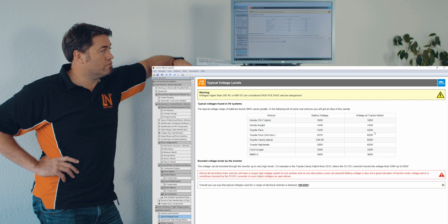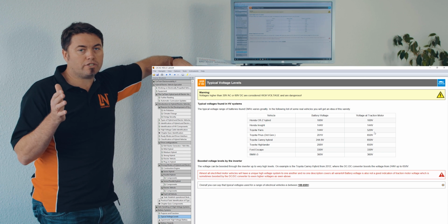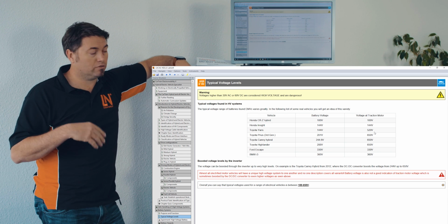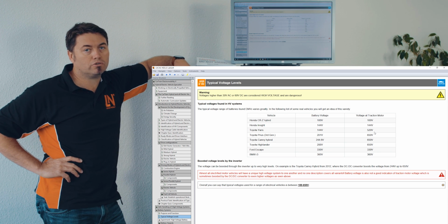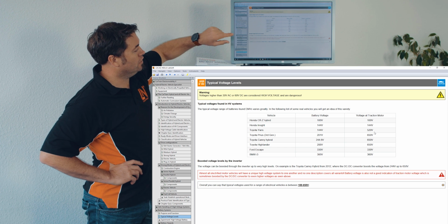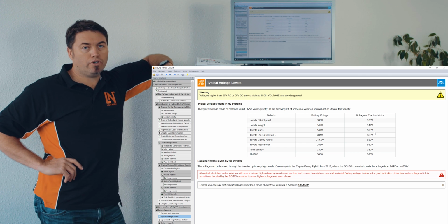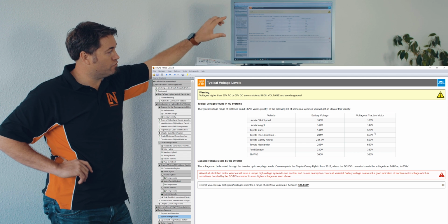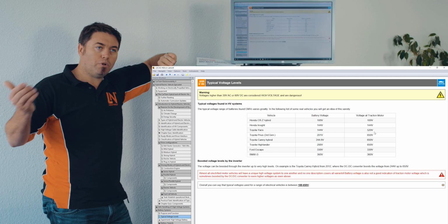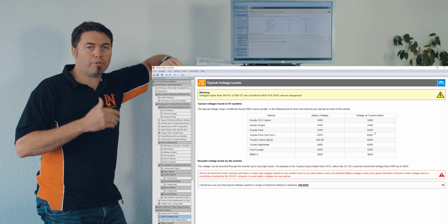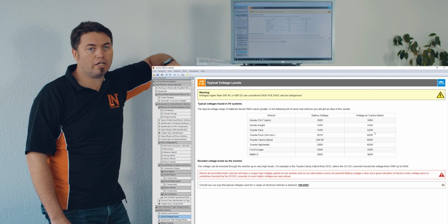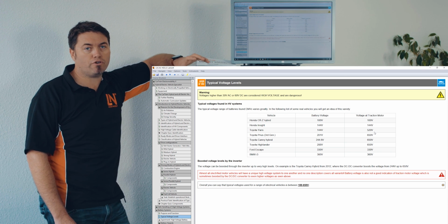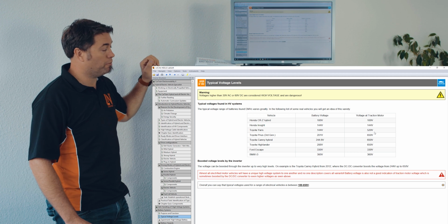And that's not always the case. It's not exactly always 600. It's varying in between. I'll also go into a little detail about that soon. So that there is what we call a buck boost converter. It's converting the voltage up or down. In one direction from the battery, obviously up to the motor. But when the current is coming backwards, then it needs to drop that voltage down again to charge the battery. Obviously, if we have 700 volts on a 200 volt battery, it will probably ruin your day.